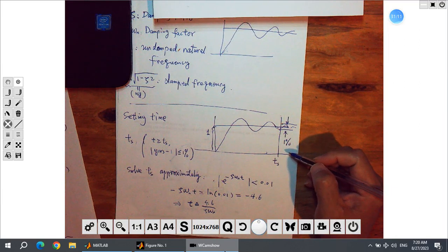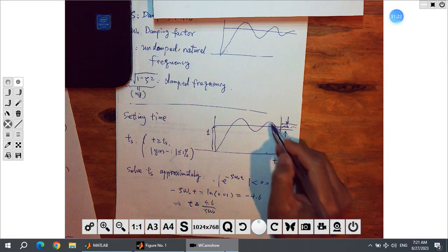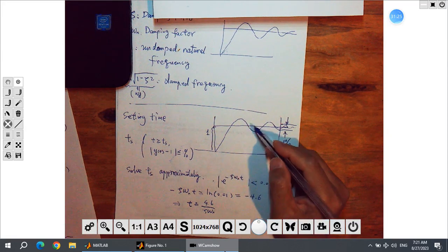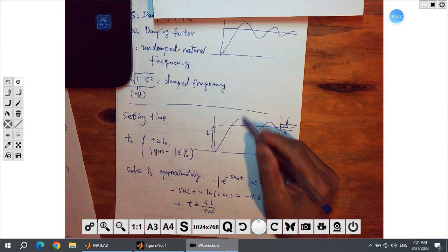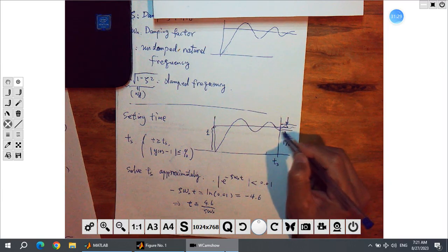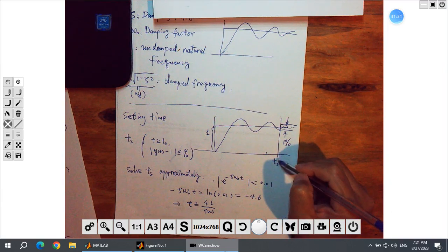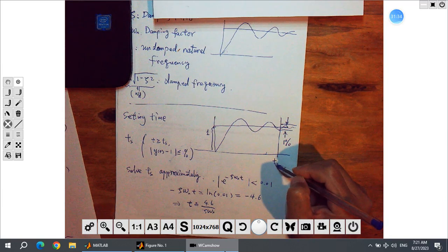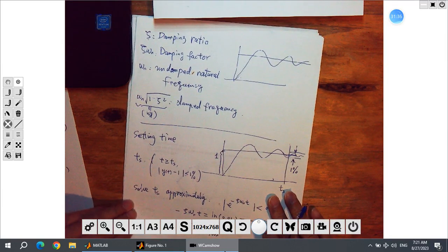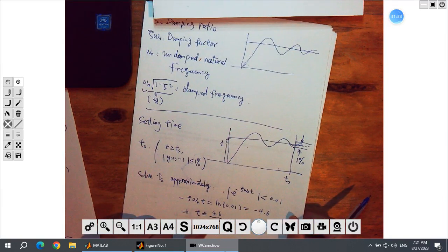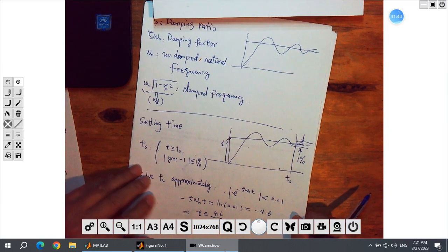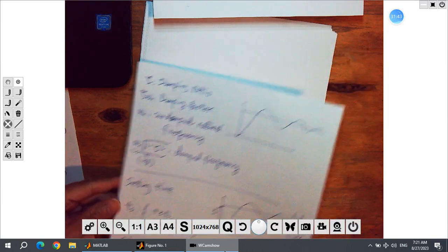That means when you start a system, you just turn it on, it will run. After a while, it will go smoothly. Right? In the beginning, for some time the system might shake, maybe overshoot. After a while, it is smooth, and that smooth state starts from Ts, the settling time. Now, of course, this formula is just for the prototype second order system.